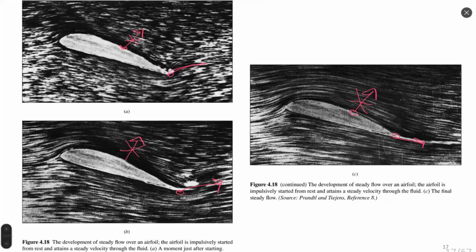So flow from top point, from top edge of airfoil does not happen in real life, only from the trailing edge. This proves Kutta condition and existence of Kutta condition, and proves that we must always take into account this equation to obtain correct solution according to our real physical process.